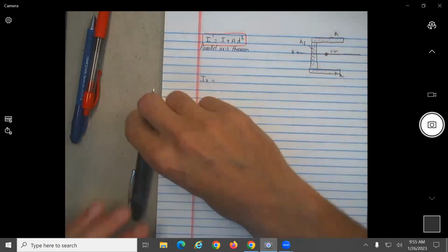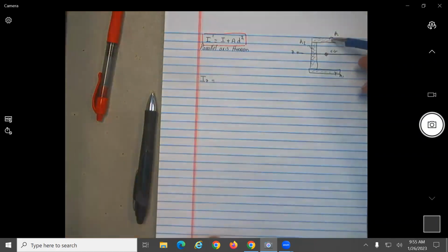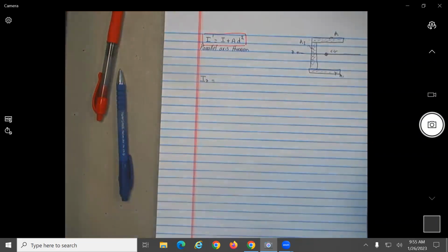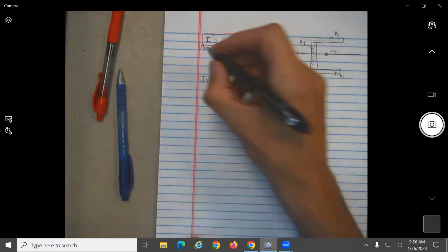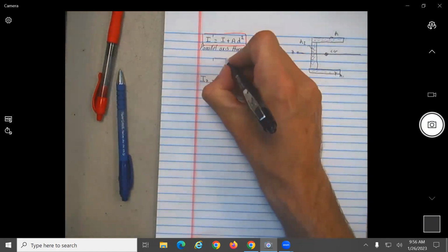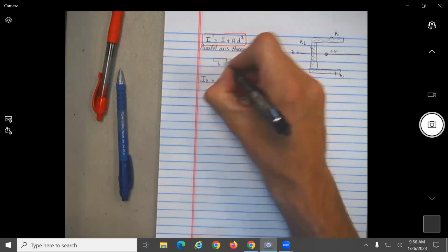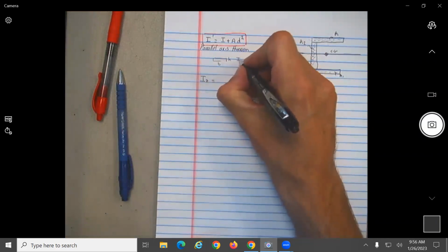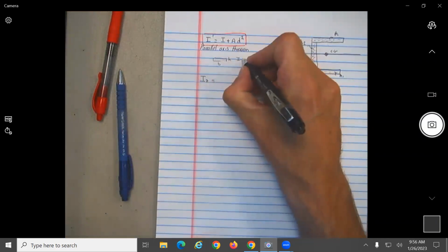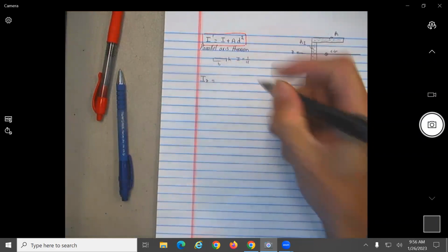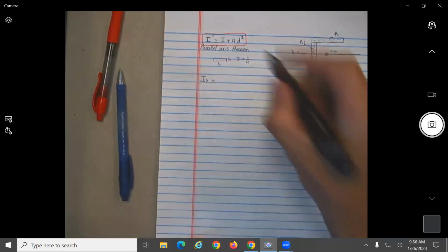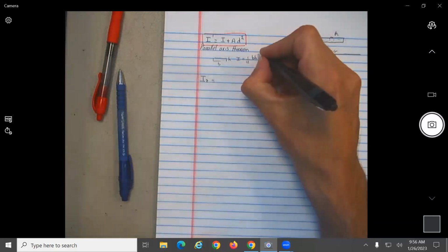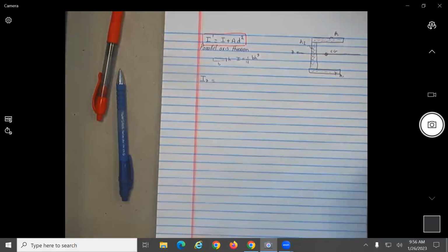So basically, now, if we have this element here, this area here, we also have an axis about itself, no? Okay, so what is, by definition, I'm going to put it here. Let's say this is B, this is H. What is the moment of inertia of this one about the z-axis? I mean, I'm not going to put too much detail, but it would be 1/12 of what? B h cubed, no? Yeah, that's the general definition, okay?